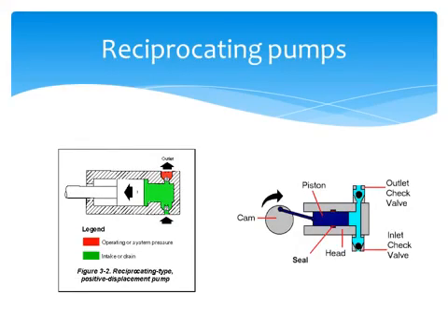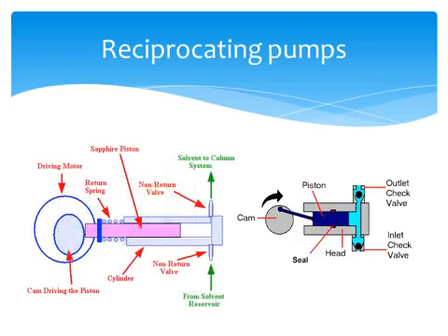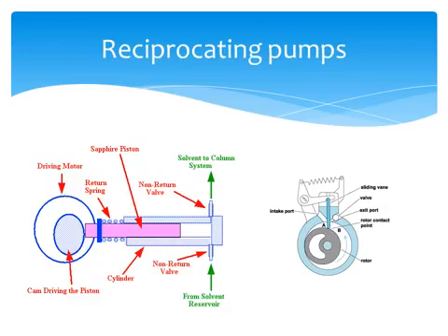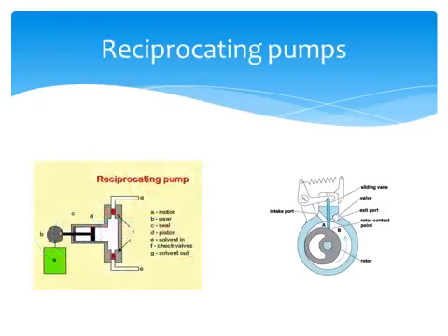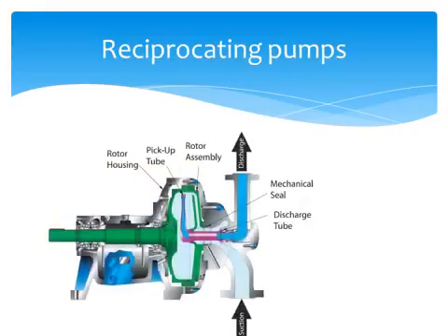Reciprocating pumps are defined as being steam, power, or controlled volume pumps. In all reciprocating pumps, there are check valves on the suction and discharge. Fluid flows through the suction valve and into the chamber as the plunger, piston, or diaphragm recedes. At the end of the stroke, the chamber is at its maximum size. The suction valve closes, and the plunger moves forward into the chamber, forcing the fluid out the discharge valve. The flow from each chamber is a pulse flow. If the pump has several chambers, they are timed to have sequential pulses, to minimize the overall pulsation.